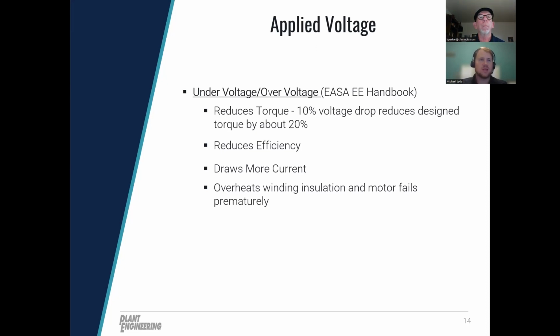We've actually done some testing in our lab that showed a slight increase in supply voltage to multiple motors across a wide horsepower range leads to increased motor efficiency. At the same time, we reduced the input voltage to the motor and saw that voltages below the nominal rating are detrimental to motor efficiency. So keep that in mind later on when we're taking some values for your motor management, doing a survey of your facility. There's some other data on this.